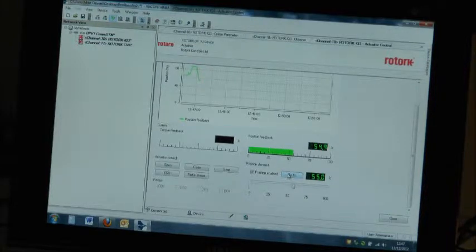But we can also use this to adjust some of the other settings to match this, deadband and hysteresis settings, which are set in order to match the actuator to the valve so that you have accurate positioning. So if you have a very heavy valve with a lot of momentum, you need to cut the motor before it reaches its desired position. So you can use this to do that rather than have to be out in the field or to use other tools which don't have nice graphical interface. So that's excellent commissioning, and it's very similar for CBA here.